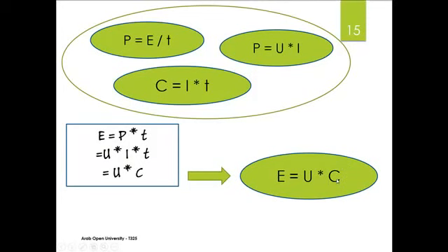And look, all these characteristics are independent from the consumption of the power. So these characteristics are for a battery that is not in use. When we start using the battery, we can then calculate the power when we have the current drawn from the battery, and having the capacity and the current drawn, we can get the time for which the battery can last.